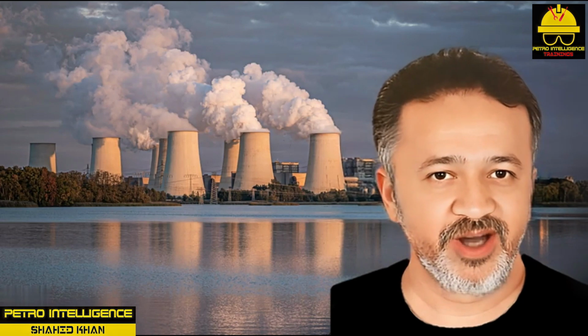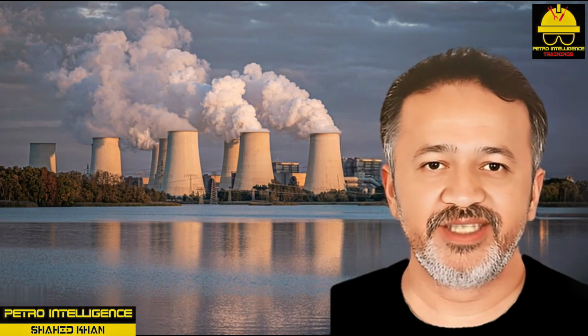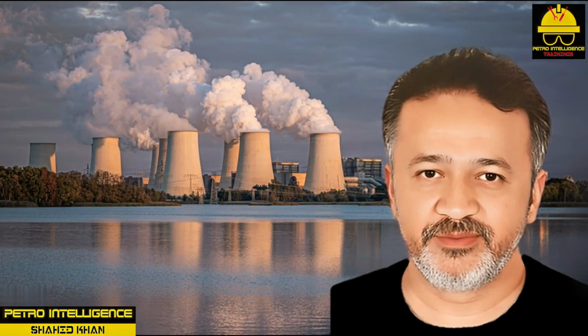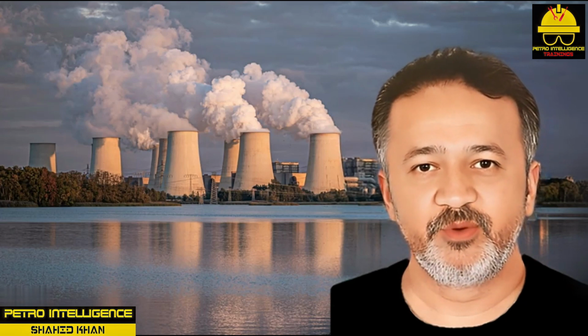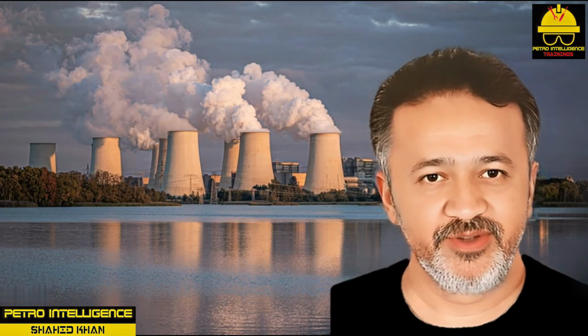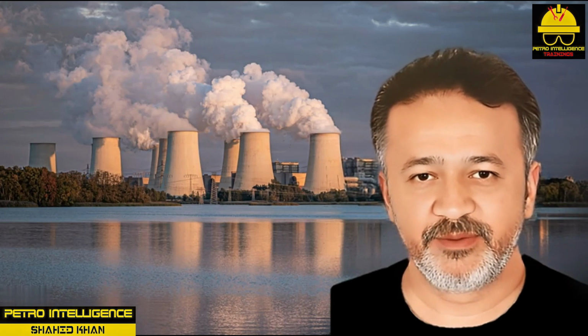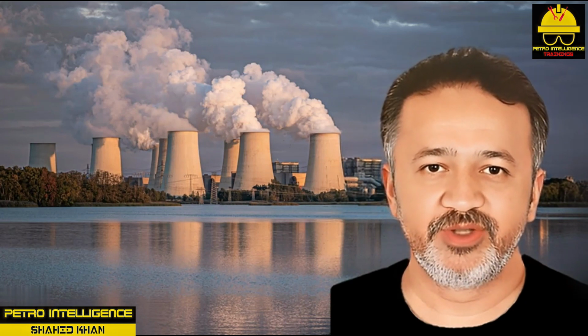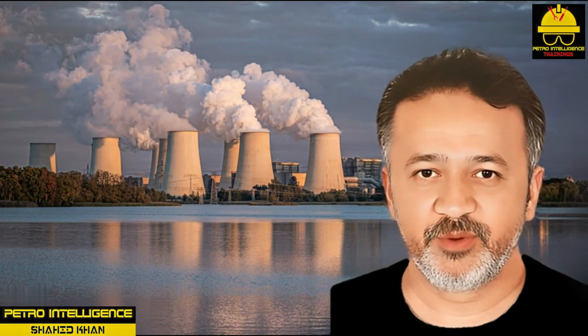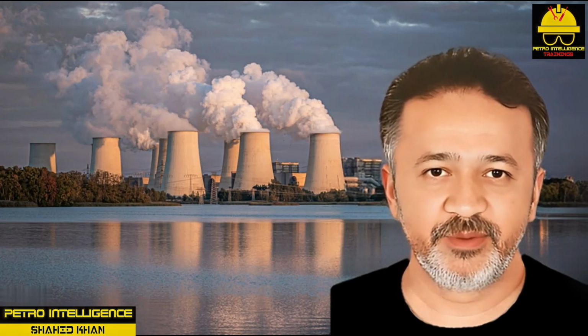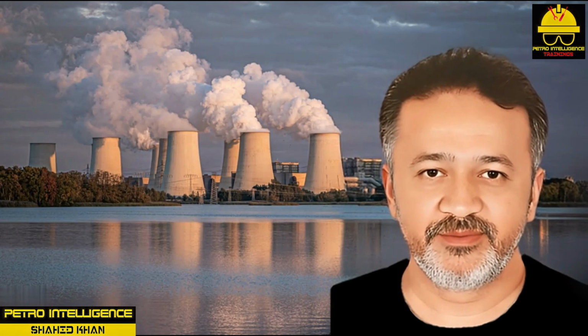The problem of suspended solids is controlled by a process called blowdown. A certain amount of water is removed from the system and replaced with fresh makeup water. Scale-forming solids can be removed with softening agents, or suspension of solids can be prevented by adding chemicals. Another approach is to precipitate the scale so it can be removed. To precipitate is to get particles to fall from suspension.